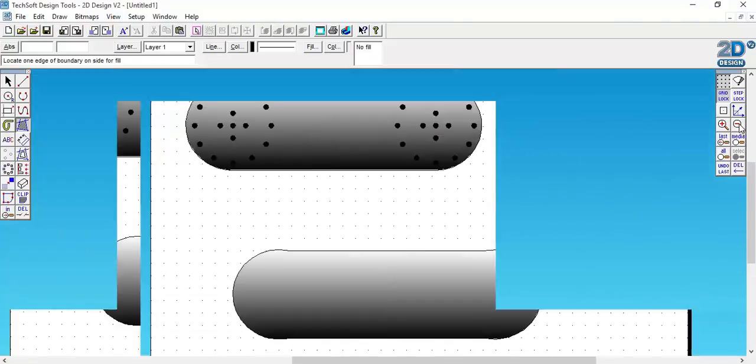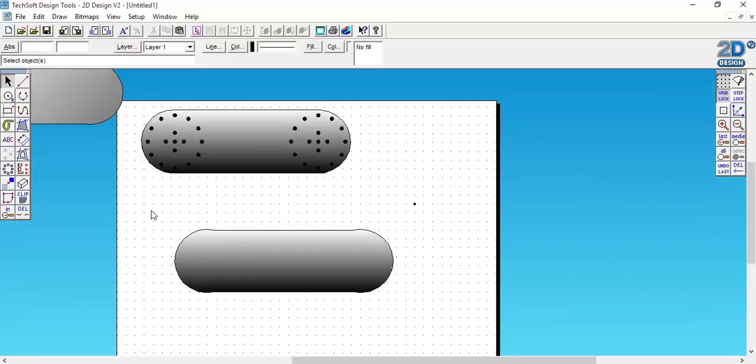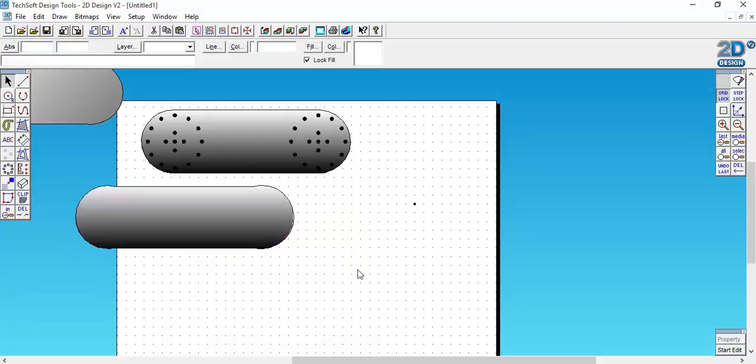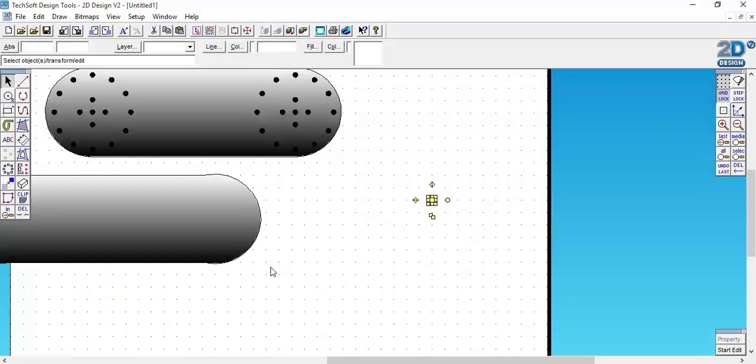Happy with that. Now the software is a bit quirky, so you need to move this out of the way before you create your speaker grill. So move it to one side, click on the circle that you've just drawn, and then what we can do is use the transform menu, and then go to this one over here which says draw a circular array of the selected objects. An array is a group of things, so we're going to draw a circular array, a circular group of circles. You'll see what I mean to create the speaker grill effect, like the one above, the one we just drew.